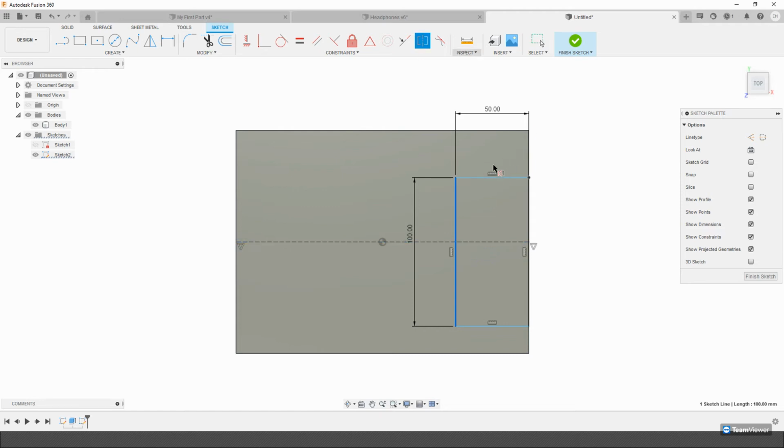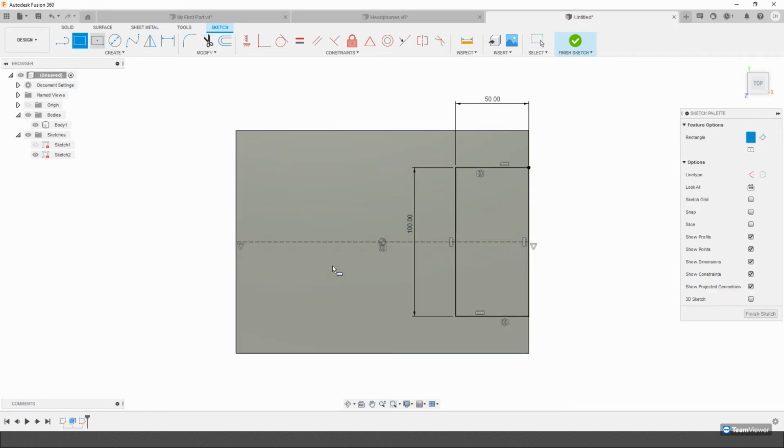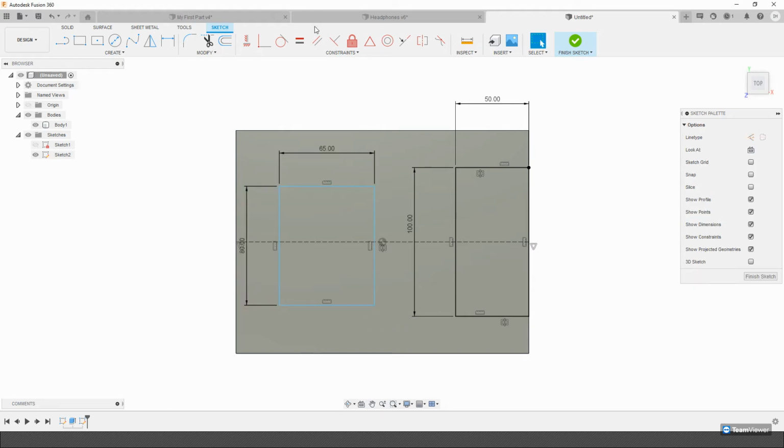How do I do that? I can make another constraint forcing that one and that one to be symmetrical about the center. And everything else stays locked. So now you'll see all these little icons, they're telling me what's constrained about what. For example, that's symmetrical about the center, that's horizontal, that's vertical, and that's at the midpoint. Right? Similarly, I'll do this on here. And I'll just say maybe 65 by... Okay. Again, I can do roughly the same thing.